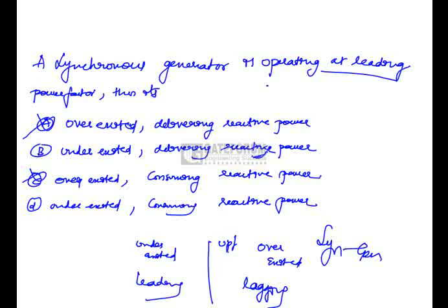Now what about the sign of reactive power? Since it is a generator, a generator will always deliver. Motors will always consume. So option B is the correct answer: under excited and deliver reactive power.